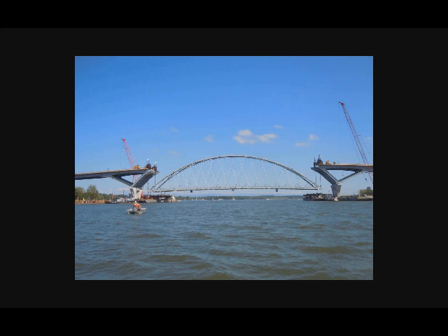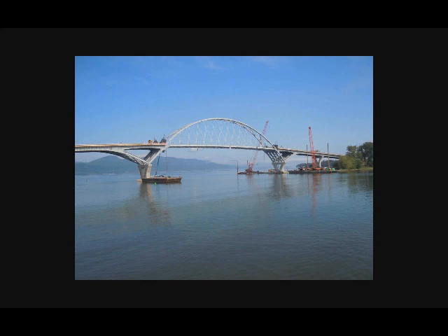And so now the bridge is just hanging from the cables, and here it is. So the bridge is out. So in the left corner, you can see there's still a piece of floor beam underneath. So the final operation is actually to install the floor beam or the support beam that the arch actually sits on in the end.